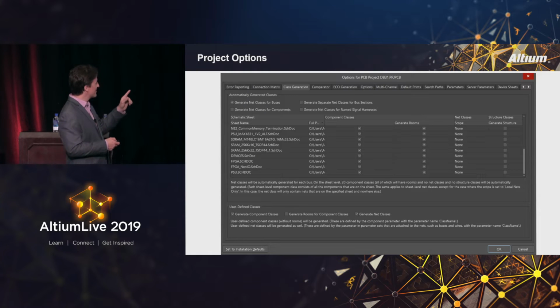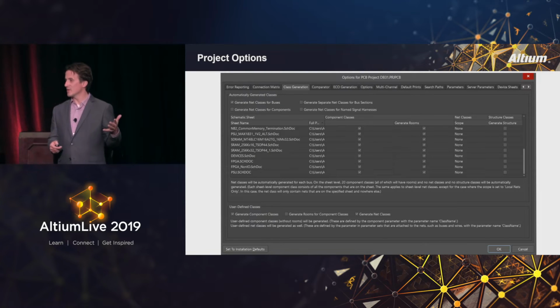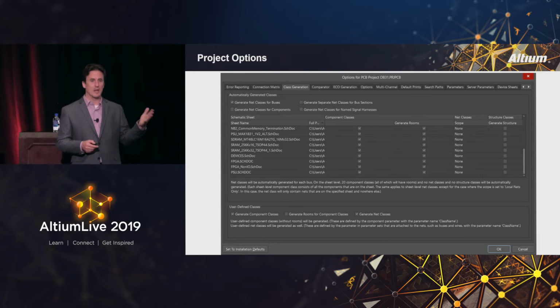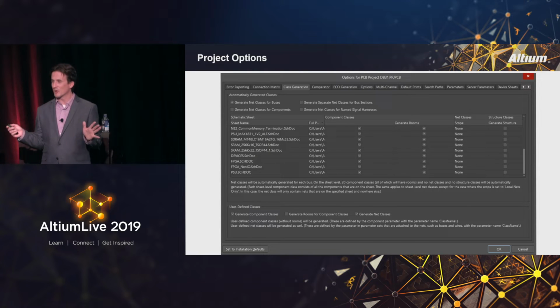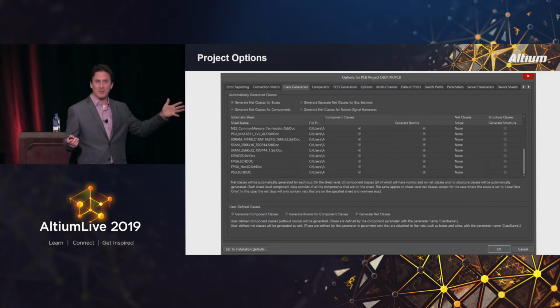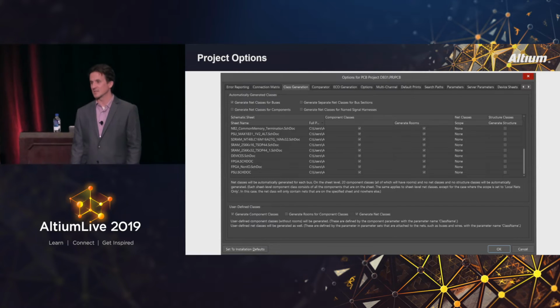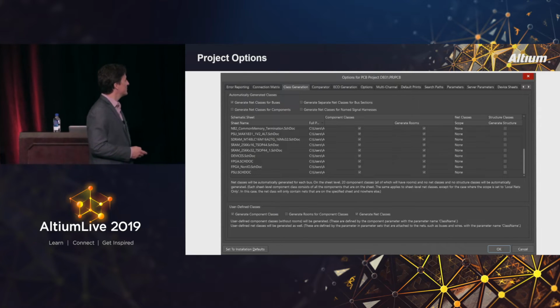The other thing that I learned, and I did not know this, I'm going to be using this a lot, is you saw that I love to use harnesses, and that I've been using, in addition to that, blankets to name my classes. But I literally learned about this option yesterday: if I do a good job of setting up my harnesses, then my harnesses can create all of my net classes for me, and I wouldn't even need to do blankets. So I thought that was pretty cool.